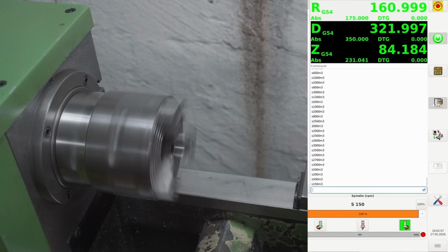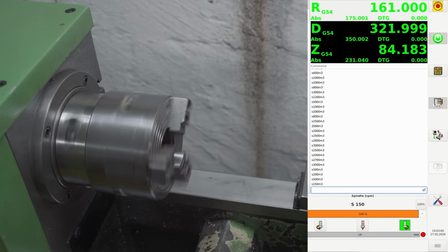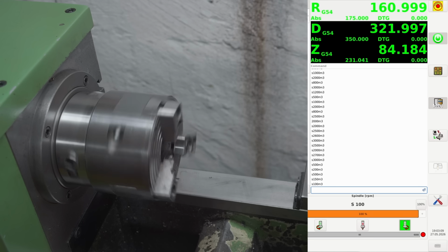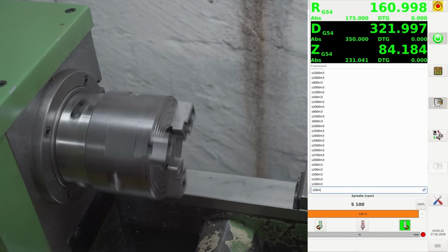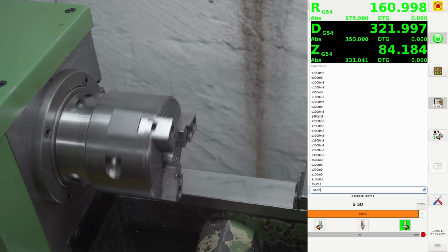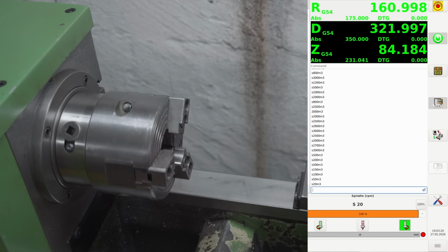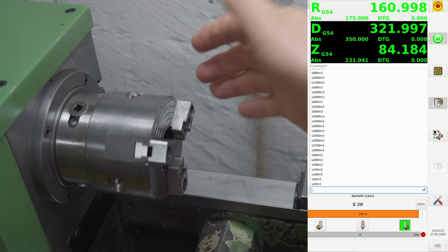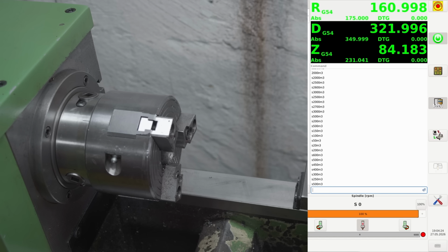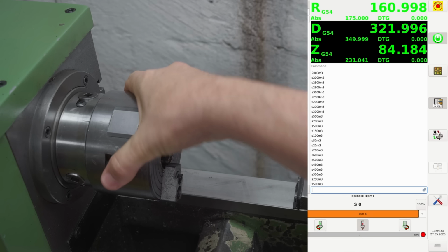I'm going to need to develop the software further to take advantage of the VFD's electrical braking to more rapidly change down from high speeds to low speeds. I don't know if I'd ever have a use for 20 RPM, but hey, the system can do it, so why not? In the lower range, the speeds are quite consistently about 10 to 15% too slow, so I might need to tweak my lookup table a bit, but it's certainly working.